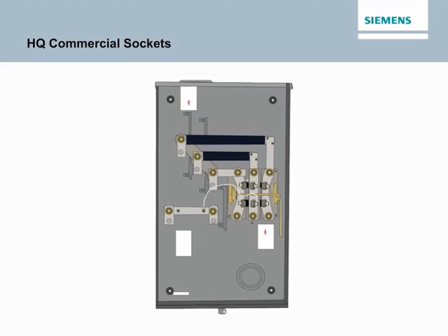However, 200 amp rated sockets are built to the same specifications as 320 amp rated sockets. 200 amp rated sockets can either have lay-in lugs or studs. 320 amp rated sockets generally have studs, but some sockets offer lay-in lugs pre-installed at the factory. Studs can be either 3/8 or 1/2 inch in diameter.